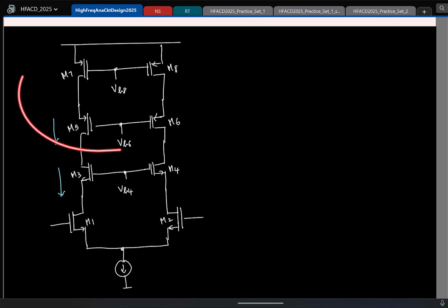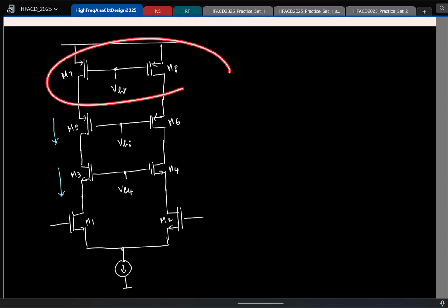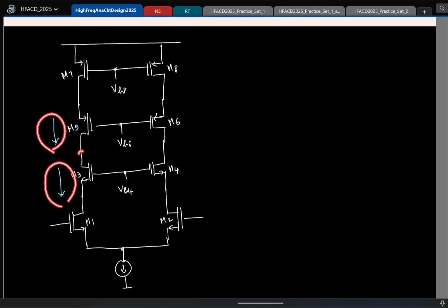Here, which is the PMOS current source? The top is the PMOS current source, remember. So if you want to change the current, what will you change? Clear? So again, can you tell me what do I do now? If this current is not equal to this current, same thing, this voltage changes. And yeah, it's the same thing. So you can essentially go and connect this.